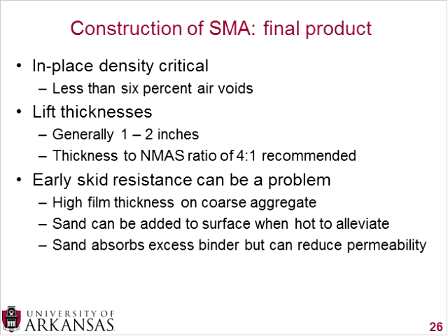And you want to make sure you do that when the pavement's still a little warm, so the sand can actually get into that top binder. Now the sand will absorb a little bit of excess binder, and it will reduce permeability a little bit. If you have a very open mix and you're dropping sand in there, obviously some of the sand will go down into the voids. But that sand that's in the binder on the top will eventually be worn away. So you don't need to worry about the skid resistance long term with that sand in there because it'll all be worn away. The sand is simply used to help with initial skid resistance.